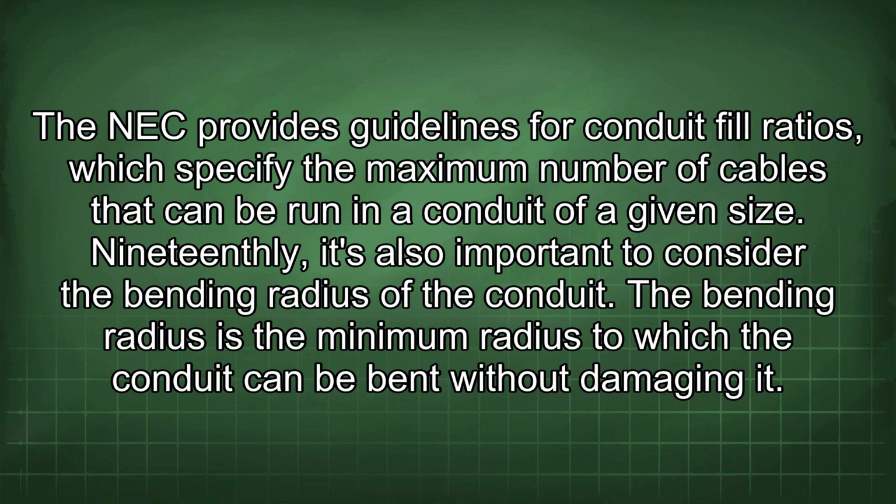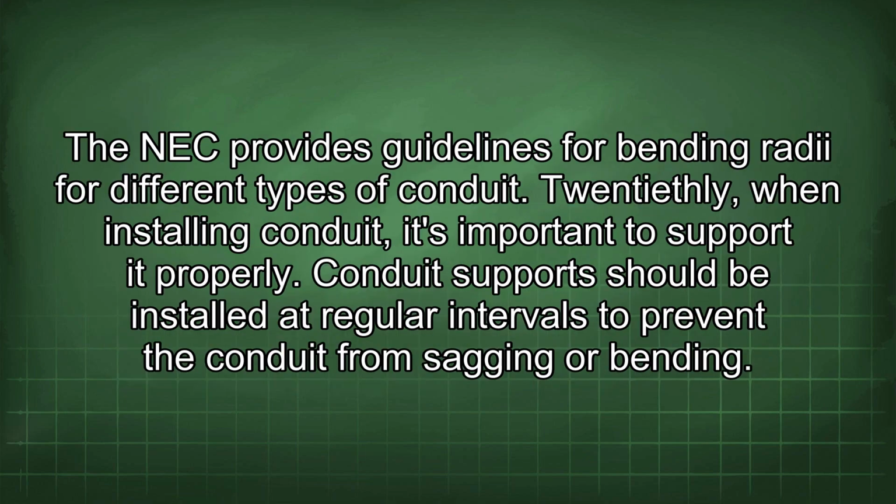19thly, it's also important to consider the bending radius of the conduit. The bending radius is the minimum radius to which the conduit can be bent without damaging it. The NEC provides guidelines for bending radii for different types of conduit.